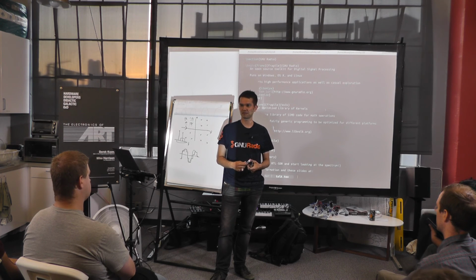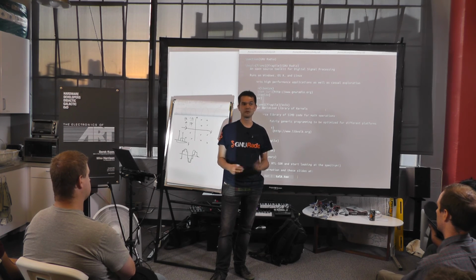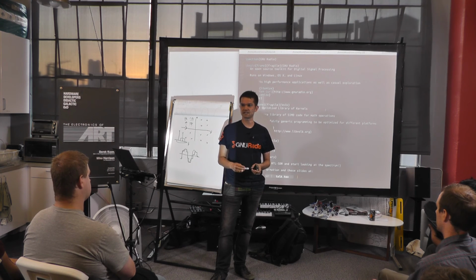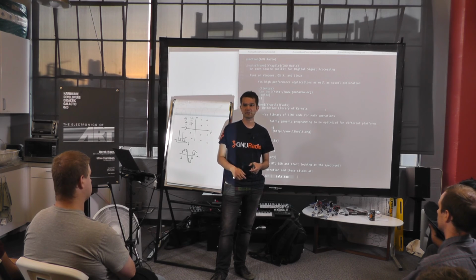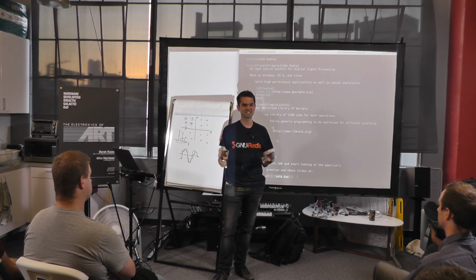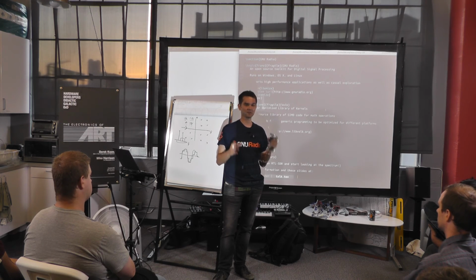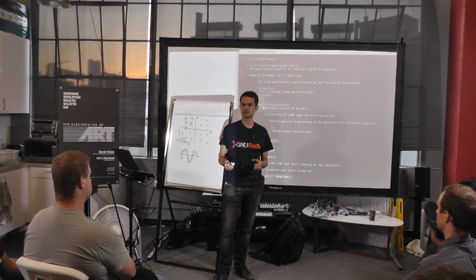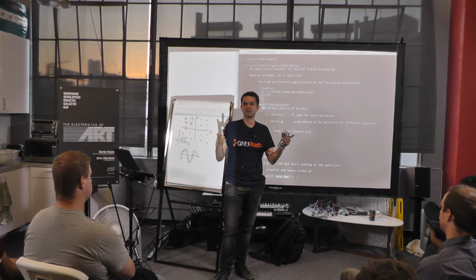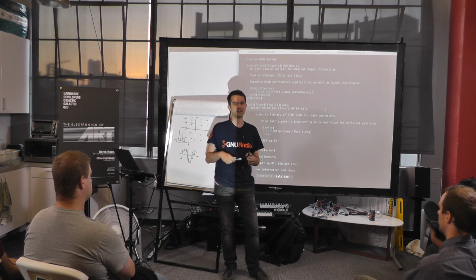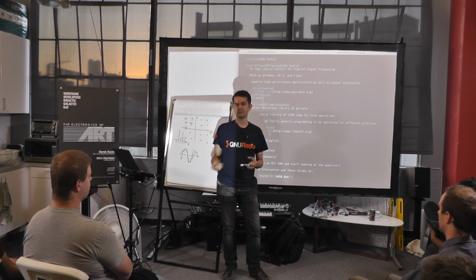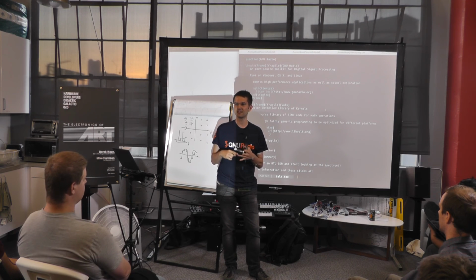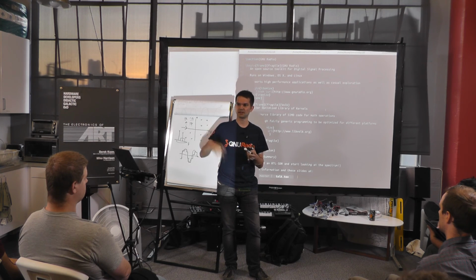Well, not anymore at 2.4 or 5.8, but amateur radio is kind of the easiest way in the United States of getting access to frequencies and the ability to transmit on them. You can transmit up to 1,500 watts. The question set for the exam is actually published online, so I really push it as a great way of getting access to spectrum. And at 10 gigahertz, we have 500 megahertz worth of spectrum from 10.0 to 10.5. So you can transmit almost anything you want on those bands. The FCC adds the requirement that you can't have it be encrypted, and they have some restrictions on ultra wideband signals and spread spectrum on the lower bands.